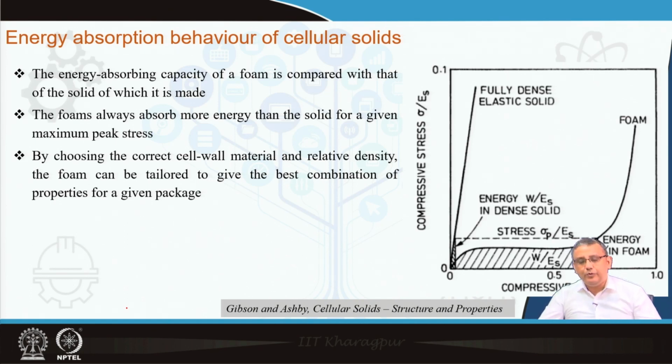Now, just assume that we have a metal which has a stress strain plot, like we can also expand it like this, because if it is a metal, then we typically expect elastic plastic behavior. So, initially in the stress strain plot, we have the linear elastic region, say we have the Young's modulus in this place, and then this point, as you can typically see, is the sigma y, or the yield point of the material. As we also know, whenever we deform such a material, the energy absorption during deformation is the area under the stress strain plot.